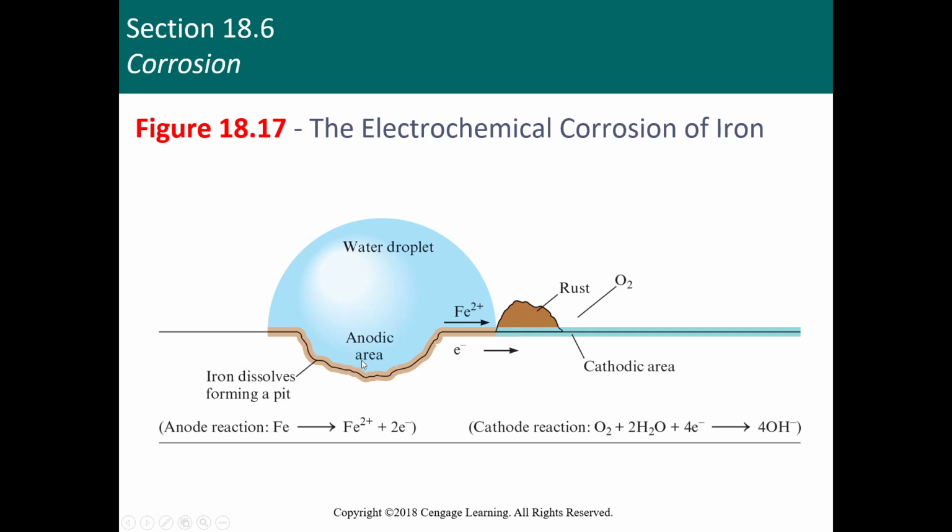So you just develop salt right here, and it wouldn't do anything. It would just stay there, and you wouldn't have any quick rusting because it would just block it from rusting more. Okay, so the iron is actually going to travel until it reaches the surface where there's going to be oxygen. And so at the cathodic area, your iron 2 plus is going to combine with O2, making iron oxide. And that's rust. And that gives you that sort of reddish brown color.